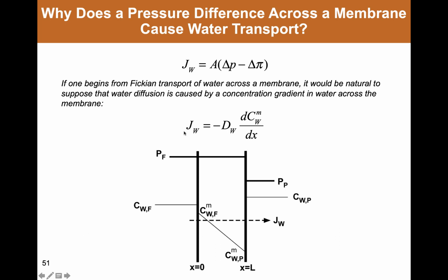And what we're trying to do is reconcile the transport of a liquid through the membrane according to Fick's law and the performance equation that's typically used to describe, for example, water transport through desalination membranes, where the water flux is found to be linearly proportional to the pressure difference across the membrane, and this constant of proportionality A is often reported in the literature as the membrane permeability or membrane permeance. So that sets the problem that we're looking at.